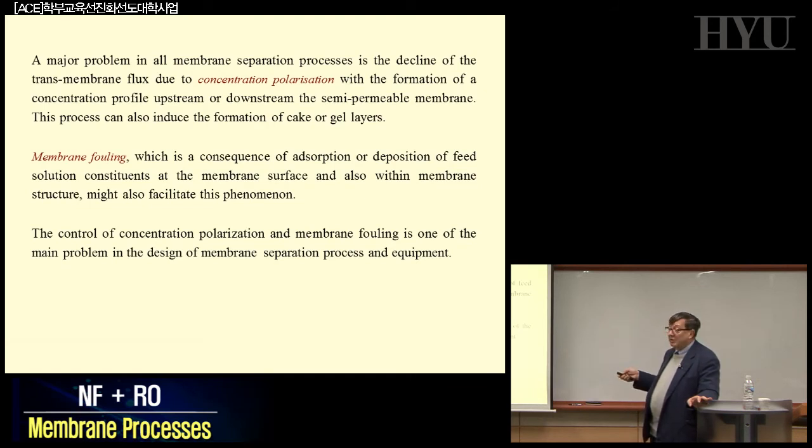Remember that there are two kinds of phenomena we are going to describe. One is concentration polarization, but after this, we will also have to discuss another problem, which is fouling. Fouling, and particularly biofouling. The two things are very separate. However, they are interrelated, because if you don't keep control of concentration polarization, in some cases you can induce fouling.